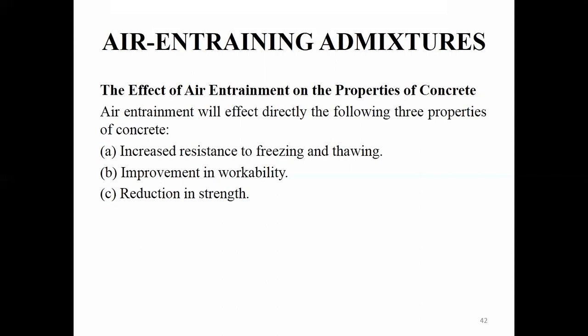See, there will be some air voids in the concrete, right? So if you need very workable concrete, the voids present in the aggregates should be filled by the cement paste, so that it will be easy for you to place the concrete. But in air entrained concrete, what happens? The entrained air increases the effective volume of the cement paste during mixing and placing. Thereby, it also eliminates the extra cement paste that is needed to induce the workability.